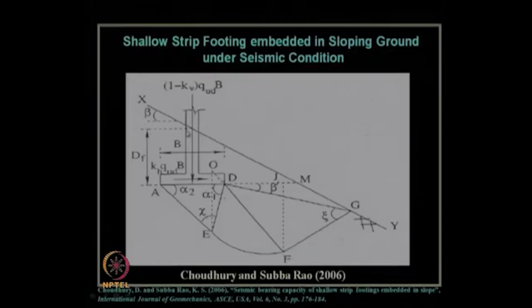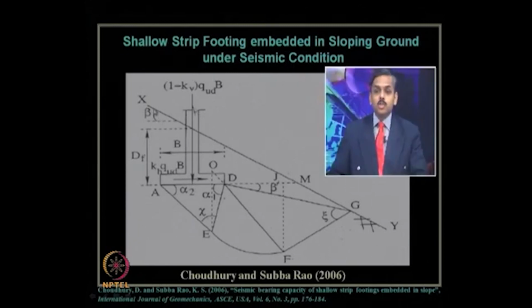Again, we discussed the design concept of shallow strip footing embedded in sloping ground. In many cases, like in hilly terrain or hilly region, we have a shallow strip footing like this, which needs to be designed and constructed in the sloping ground. So, how to design that? The details are given in this journal paper by Chaudhary and Subbarao, 2006, in the International Journal of Geomechanics, ASCE, 2006 issue.